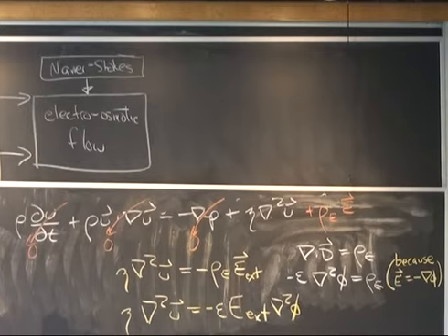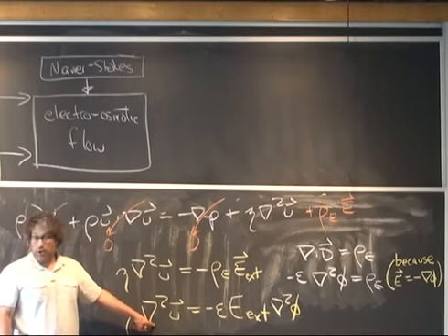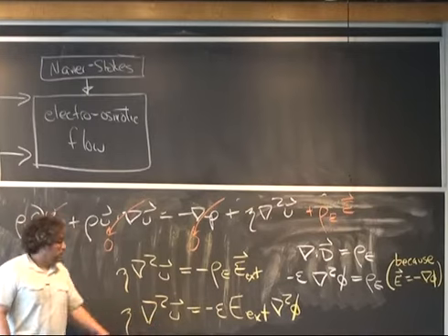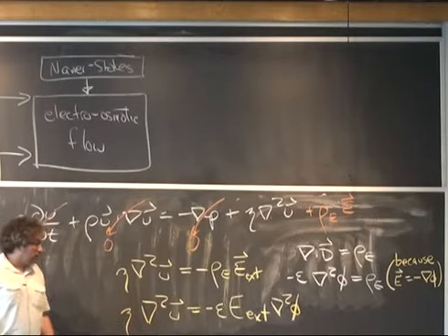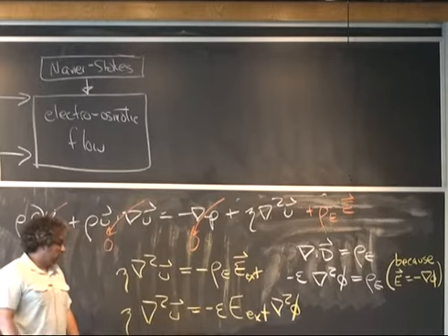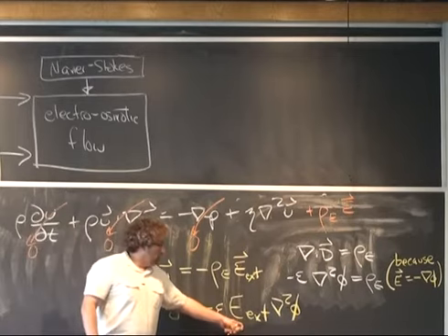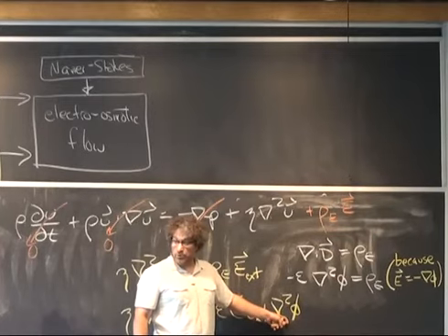I get this relation. So it basically says the volumetric viscous force is given by the Laplacian of the velocity, because I'm getting viscous fluxes associated with the gradients and I want to take that divergence. Here I have a Coulomb force, an electrostatic force, that's given by the permittivity and the electric field and the Laplacian of the electric potential.